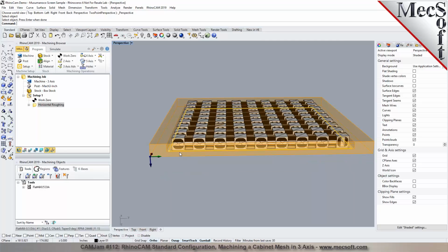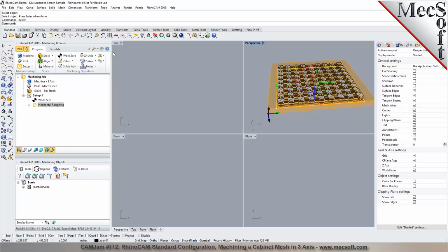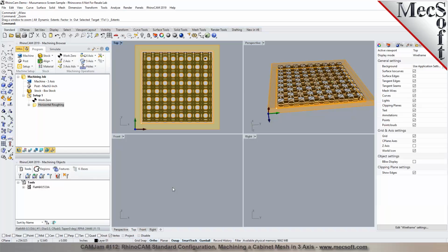Right. So there's different ways you can handle that. You can not cut all the way down. Say you can cut maybe down to 1/16 of an inch away from the middle, okay? Or you can model just some square blocks that go all the way through the part from each side. Yeah. And we can do that real quick, and I'll show you how to do that if you would like to do that. Let's do this here, and let's make sure that we see everything here.